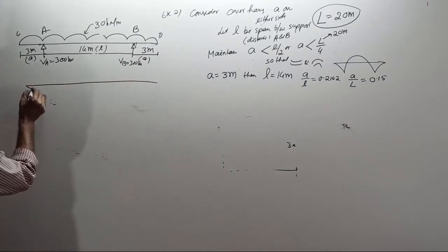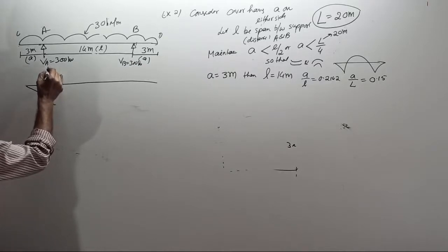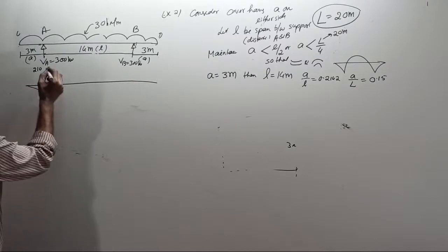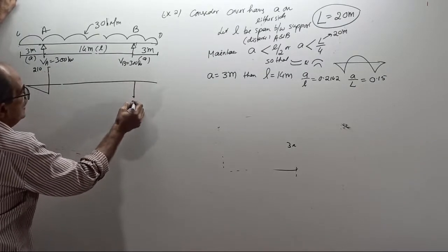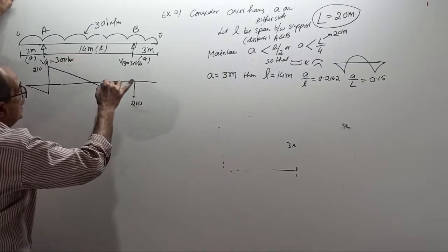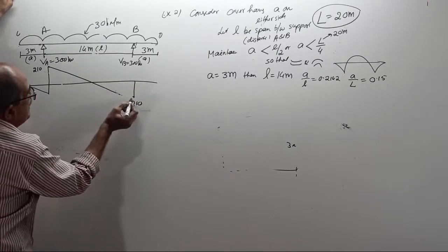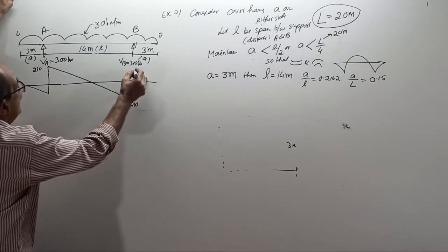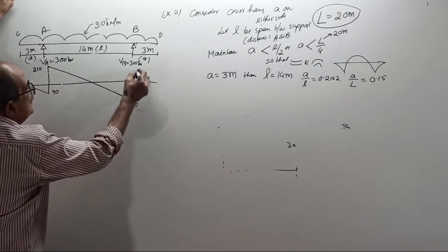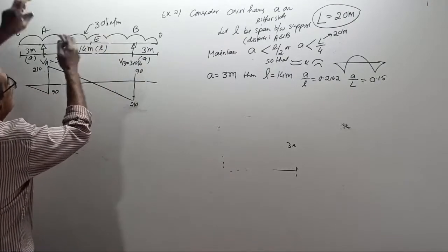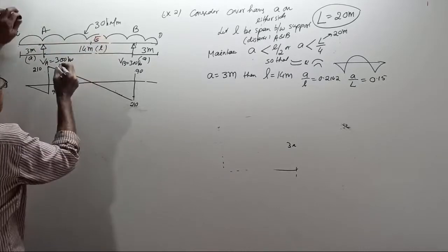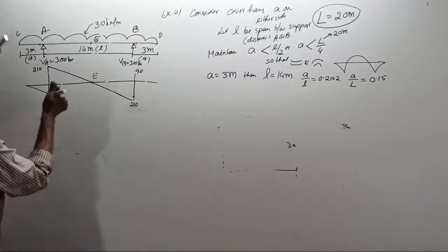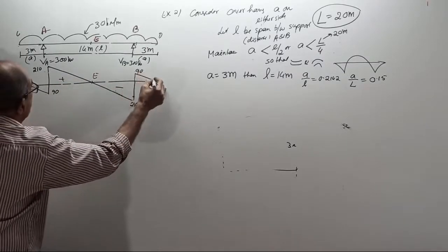Now 90 here, shear force only 90 here. Here it will be 210. See, the higher value 210, 90 will be less, 90, 210, here also 210. Okay, exact scale is not maintained, adjust. Then here this is 90, this is 90. The center is E, a special point, and then plus and minus come back to 0.